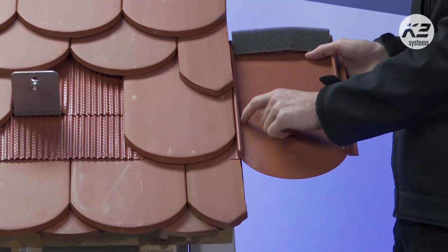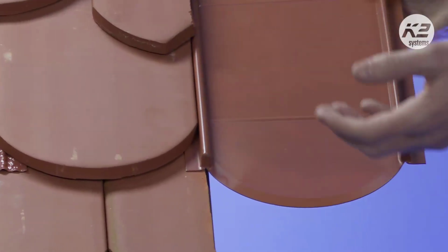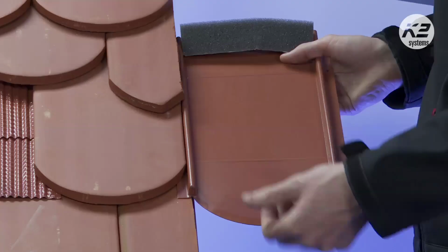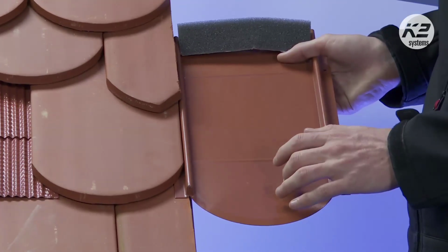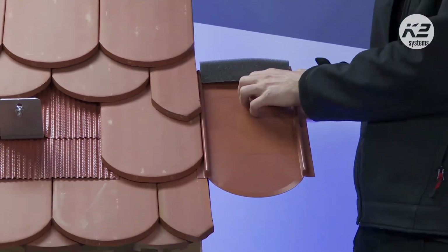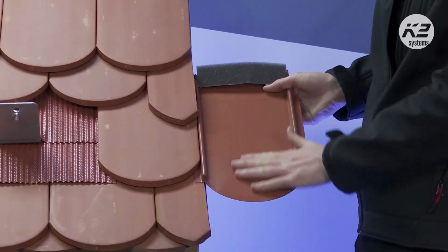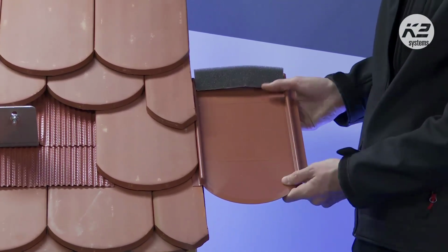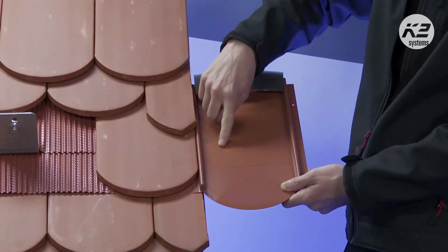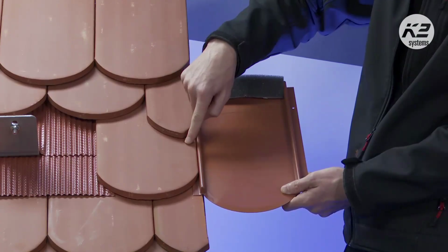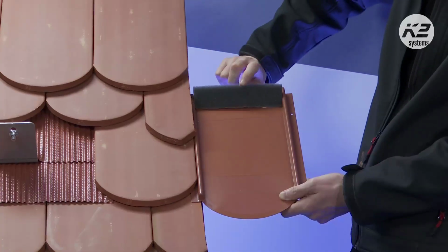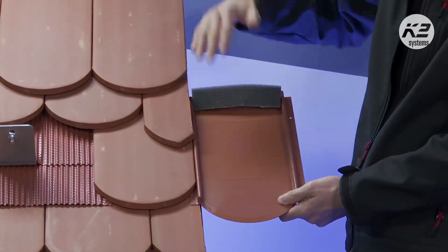barrier with this metal tile plate, and then you have this. The height effectively has been taken away, so it is still there for waterproofing. Any water that comes down over the top is just going to land onto this tile replacement and run down further. And now there is enough space here between the metal base on the top of the neighboring tile and the bottom of the adjacent tile that a roof hook could sit.